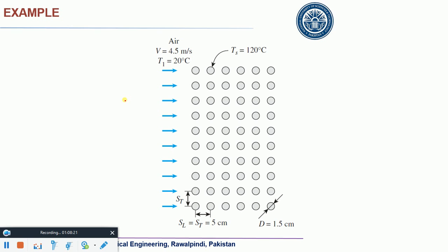From that Nusselt number you can go to the heat transfer rate, and then you can find out the pressure drop, and then you can find out the pumping power. You just need to go to the appropriate relationship and appropriate table. Every other conceptual thing has been discussed.